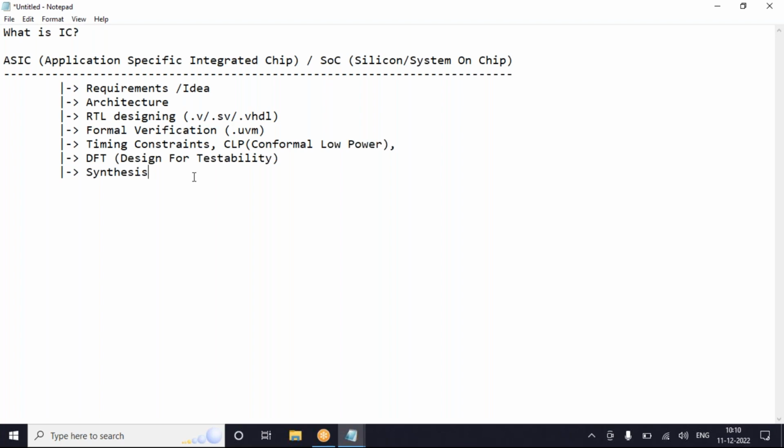It's a sequential circuit. According to the internal code, it might be working as a latch or it might be working as a flip-flop, right? Positive edge, negative edge, level triggered. So based on that particular requirement, we will be converting that to its equivalent cell. The tool is going to do it, but we select it. Okay, converting the logical to a physical entity.